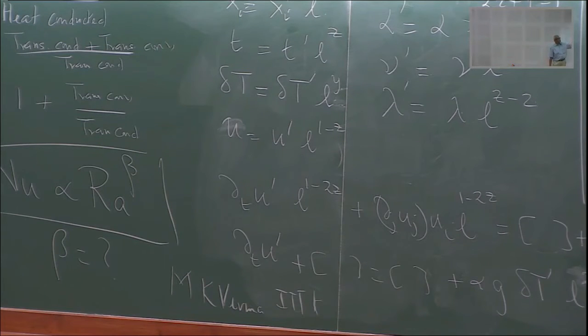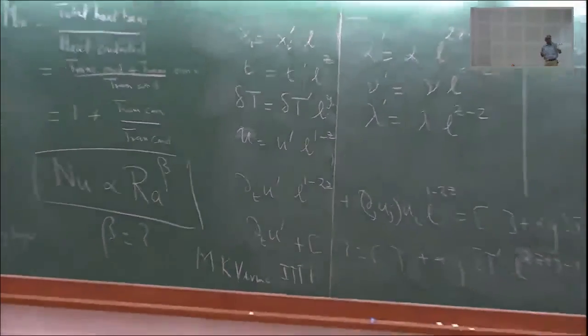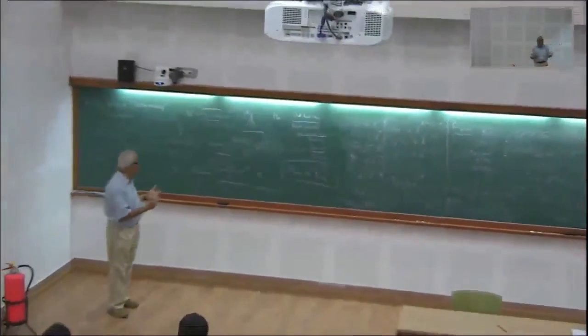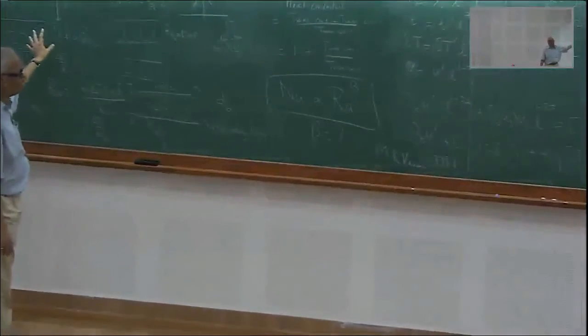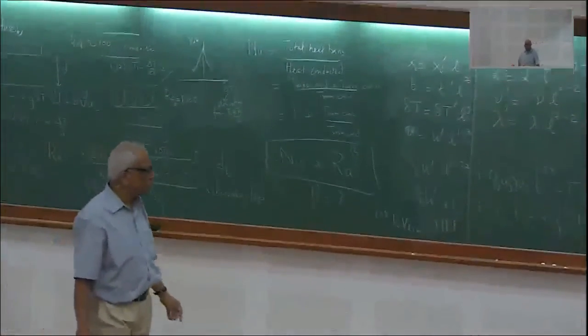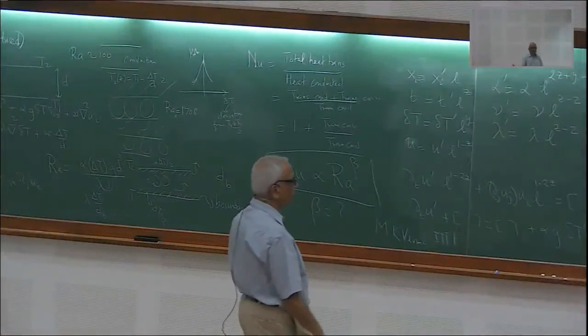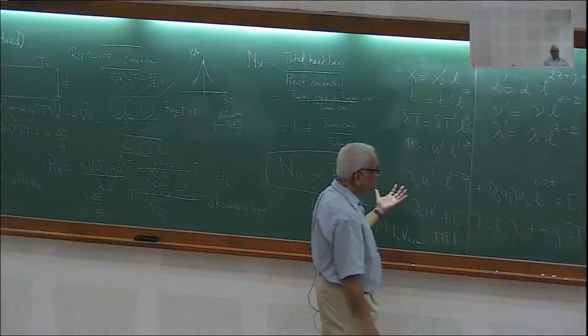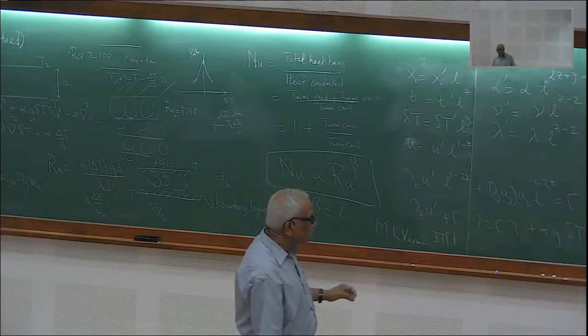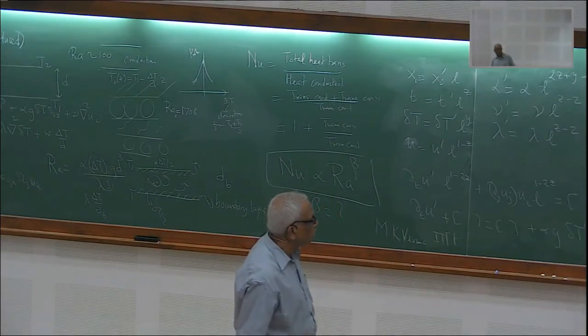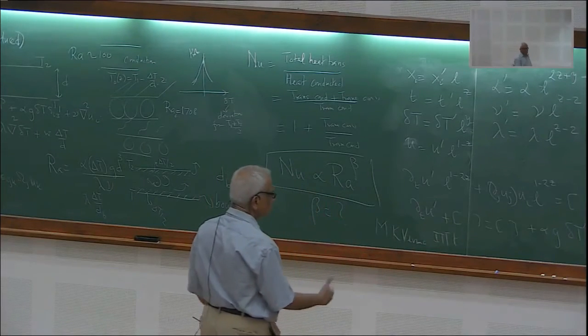The relative relation between the buoyancy term and this term is provided by the Richardson number. So the Richardson number has to be such that the buoyancy dominates. If there is a domination of that and heating from above, you do see the 11 by 5. There is subsequently another study with a rotating system which does show the 11 by 5.